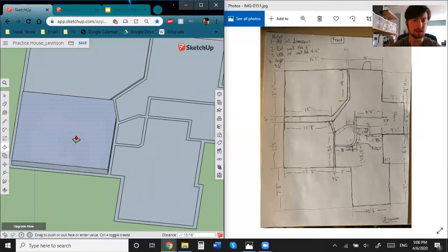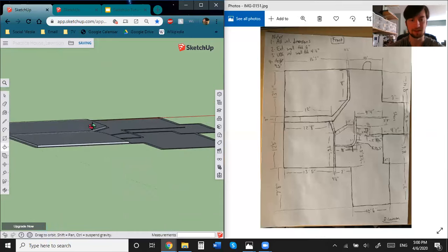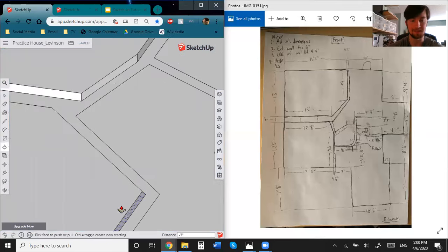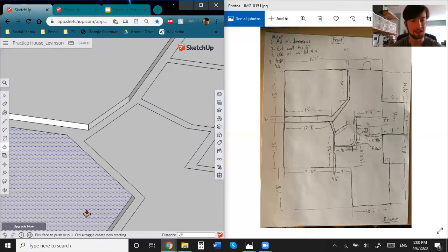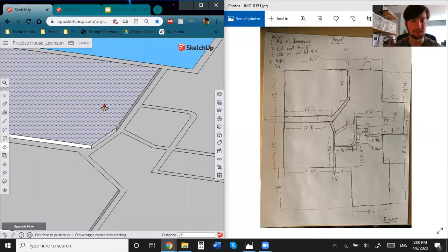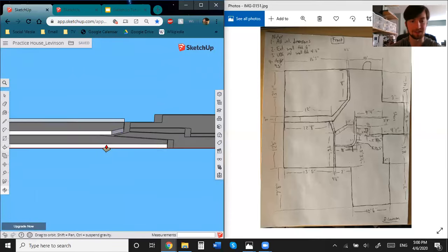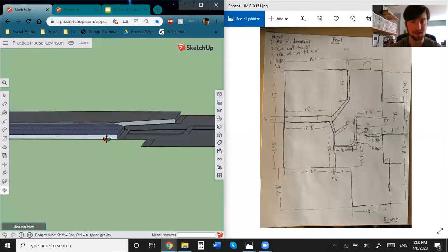And look what happens if I try to extrude this by 3 inches. For both of these, you see how it's not even 3 inches thick. That extrusion made it kind of like a shell, but that's not what we want. We want it to be 3 inches thick.